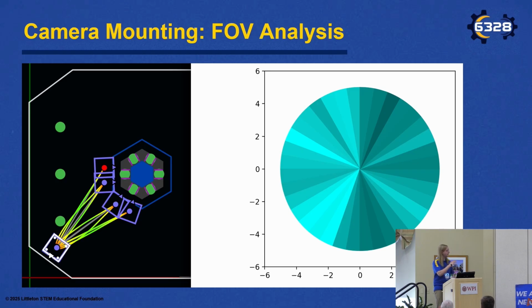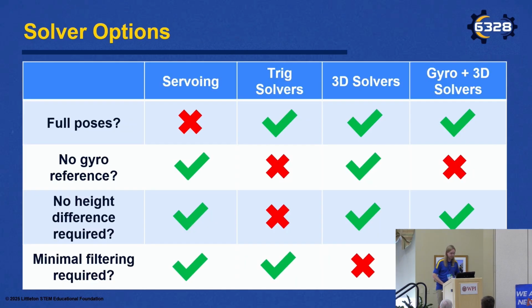And what you see here is actually not uncommon, that for a lot of games and a lot of use cases, if you account for typical robot patterns, the distribution of tags around the robot tends to be relatively even. That's hence the recommendation for maximizing the total field of view. You want to maximize the time that you're seeing any tag, even imprecisely. Now, you can also, of course, analyze this for specific games, specific robot movements, in case there are ways to optimize further, bias your cameras towards one direction or the other.